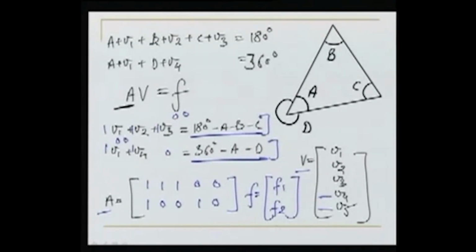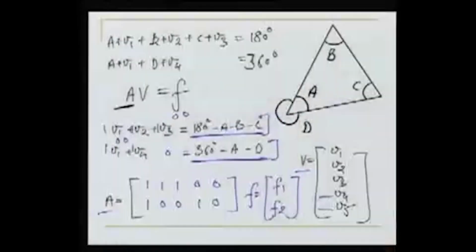So what we know now at this stage, we know A, we know F, and we know in our method of condition equations, if we know A and F, we can find K. Once we find the K, we can also find the V, and once we have found the V, we can find our parameters. Okay, so the important thing was forming these basic matrices, then rest it is simple matrix manipulation. So we can solve this particular problem by condition equation method in this way.